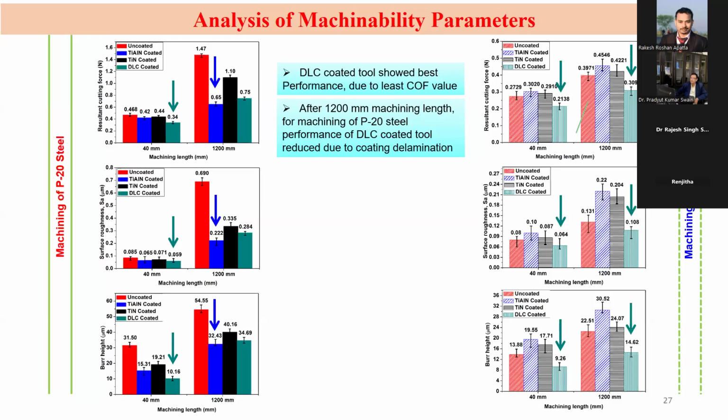And for the machining of the other material, the DLC exhibited the better performance. So here, one thing is very clear. That means we should convey this message that if we want to machine or micro machine the titanium alloy, then although these coatings are at the front line, we can't use them because more adhesion will occur. So, considering the cost aspect, we can use an uncoated one, or we can use a coated tool whose constituents should not fall under the category of titanium, aluminum, or vanadium.